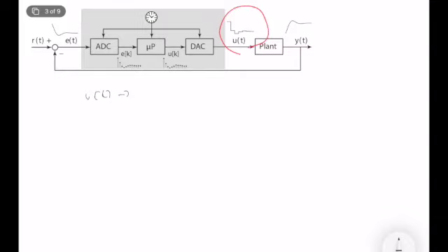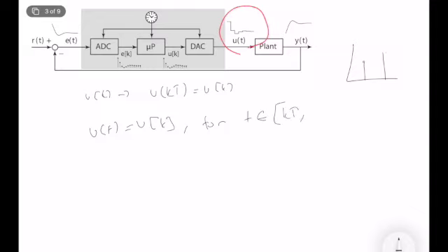So you can say that we know that u(kT) is equal to k times T. Okay, so for that, let's show them u(k). We know that, but this is at this sampling instant. I need to fill in the gaps. It's very simple. u(t) is technically equal to u(k) under zero order hold, right? And for t an element of [kT, (k+1)T).